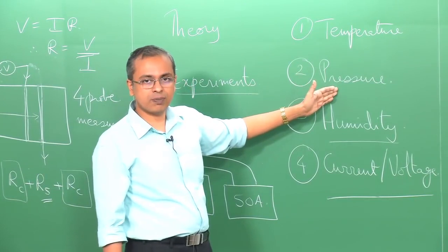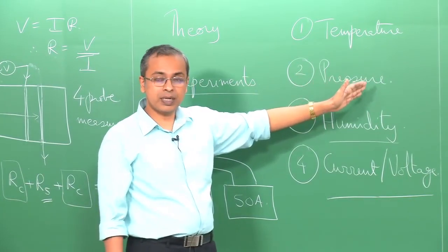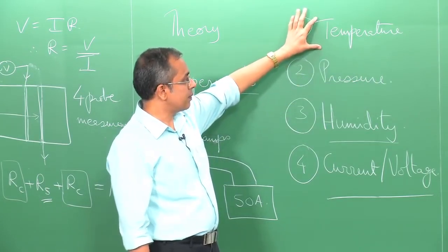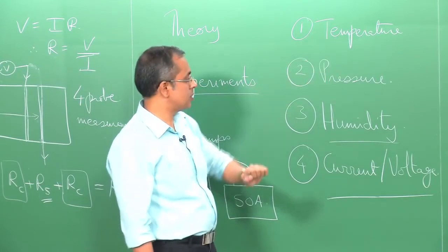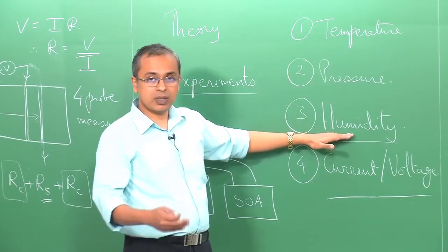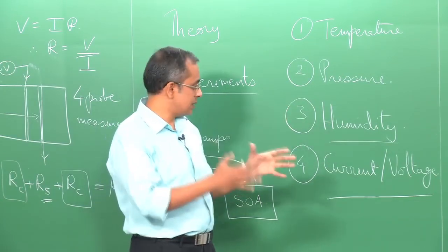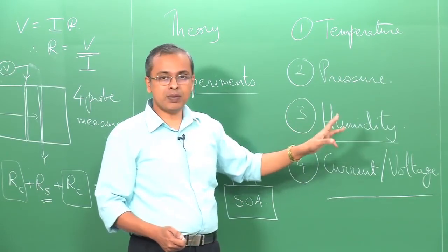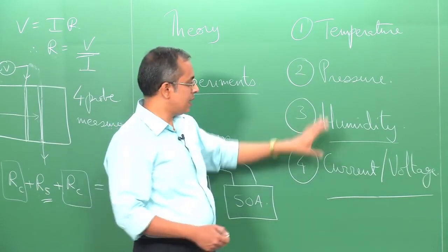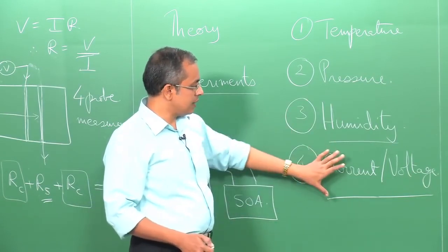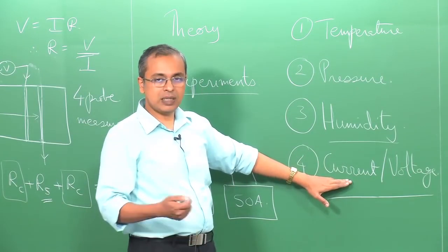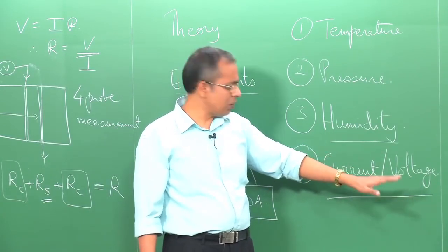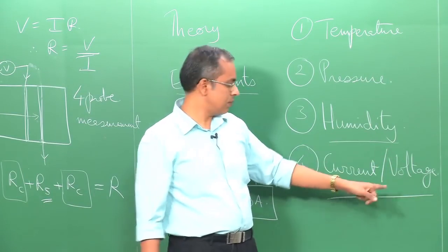Similarly, where you would put your sensor here for pressure, what kind of impurity or dirt, for example, covers the sensor, the location of the sensor or any other impurity that is on the temperature sensor also, the humidity value based on the actual temperature of the system that is humidifying it, the design of the humidifier, the design of the pathway between the humidifier and the actual experiment. The humidity value could be wrong. Based on how you measure your current, you at least need to cross check the value of current, and the location where you measure the voltage could change the voltage, and may not change the voltage, but it will change the significance of the voltage because that is different.